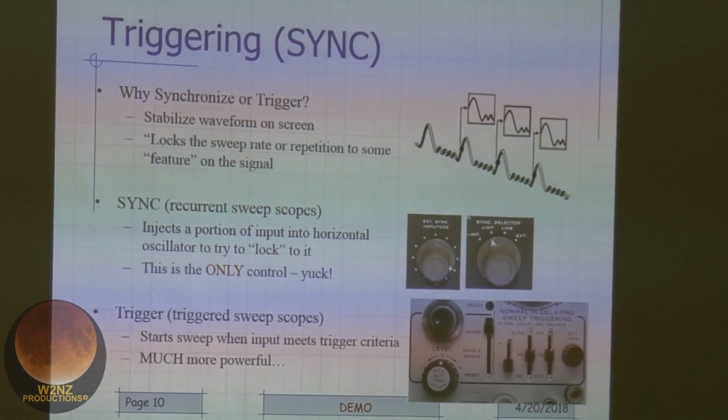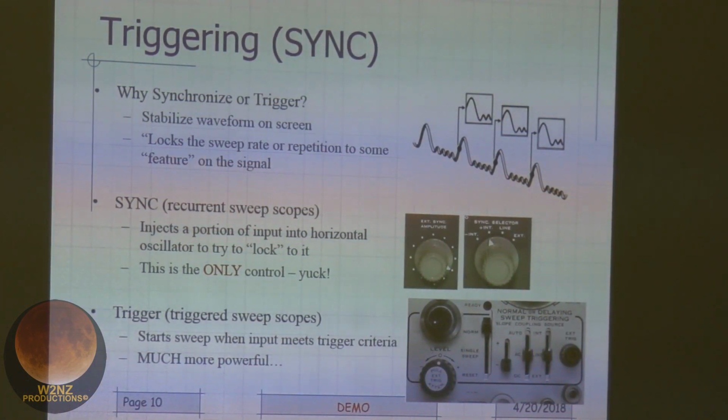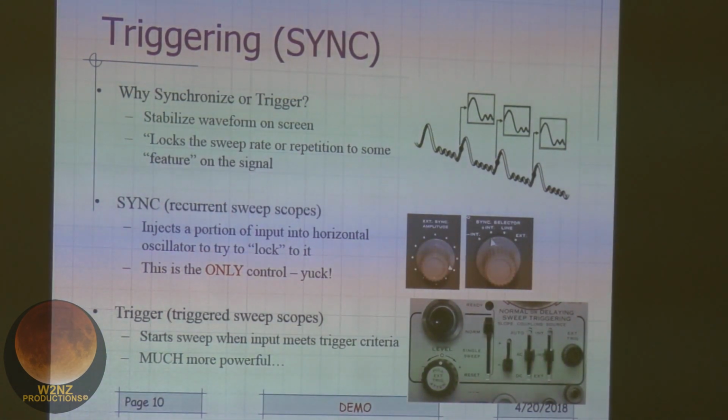And if you tweaked around with the vernier control and horizontal, and you just tweaked around with the sync amplitude, you can kind of get the waveform to be stable. But nothing was calibrated. It's just a pain in the neck. So I say, yeah, it really is not what you want to use.